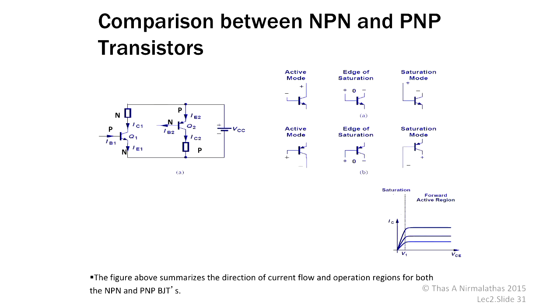So, comparison between NPN and PNP. This is another advantage. When you have NPN and PNP in the same circuit, if you follow this kind of inverted mode, then you can give the same bias. Drawing is easy. Otherwise, for this one you draw a separate circuit, and for this one you draw a separate circuit and connect the bias. But if you rotate it and bring the emitter here, then you can connect the same voltage. See, both the circuits are now under a proper bias. But then you have to reverse it, as I said. Then it is easy. That is the reason you will see it this way in Razavi's textbook.